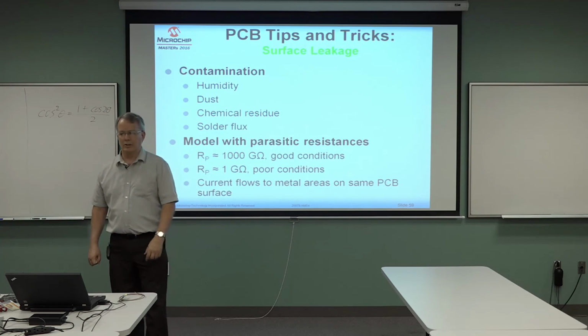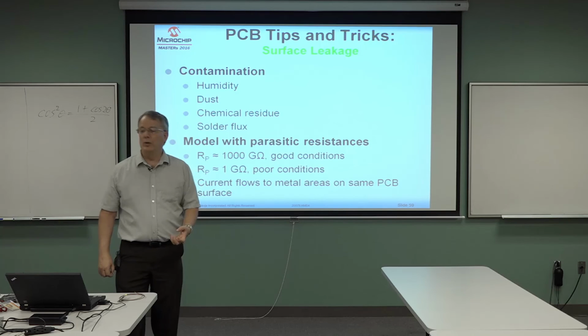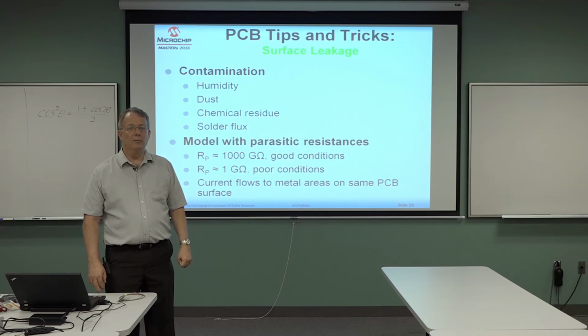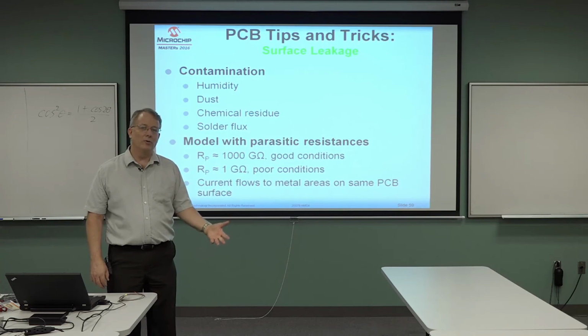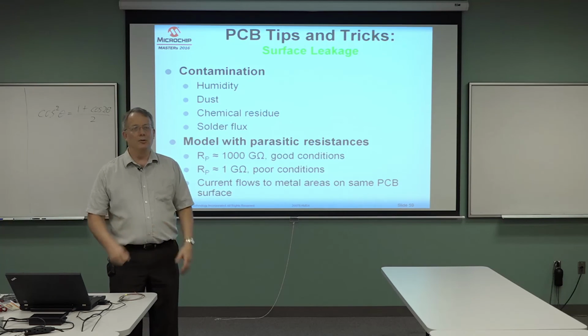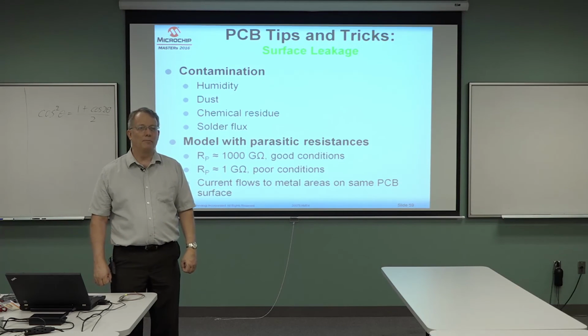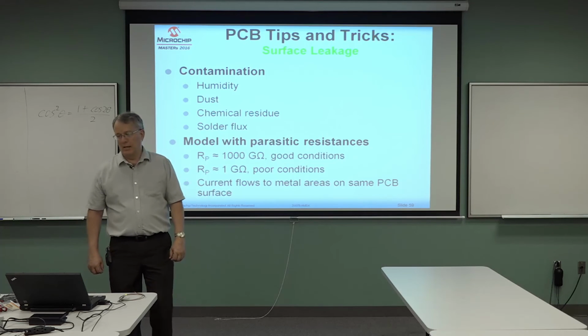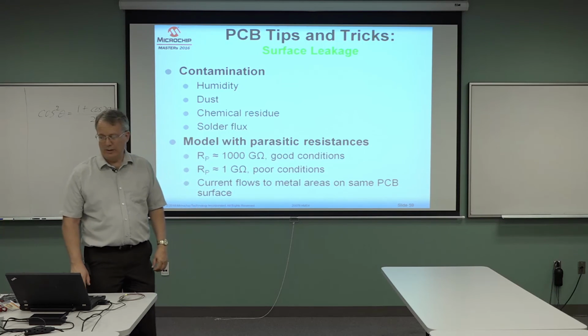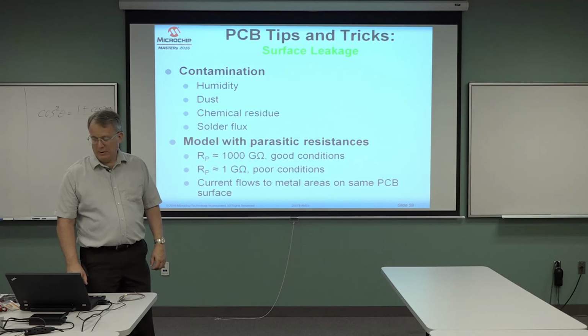We found that if we left the board with just the standard solder flux remover residue there, we would get a couple of microvolt error. And our technician found that if he used Windex as the final clean, we were able to get where we needed to be. So our standard flow now is do the standard printed circuit board build and clean and all that, and then go and use Windex to clean it one more time. You may find another final cleaner that you like better, but that's the one we've ended up with.